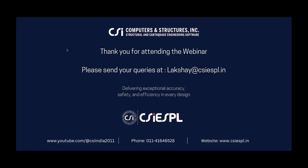The modeling is the challenging part, which I wanted to demonstrate, to show how easily you can do this. I took a lot of time to explain everything, but if you do it yourself, it may take 10 or 15 minutes to complete this model. And you have full control on the member section properties. Once it is done, you can simply update these properties, rerun the analysis and design, and do the iterations.